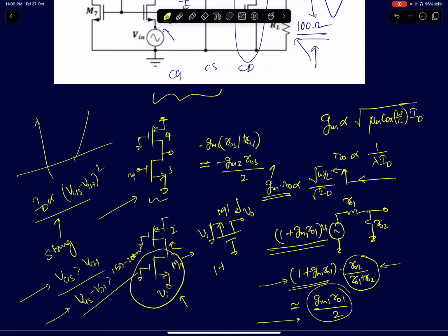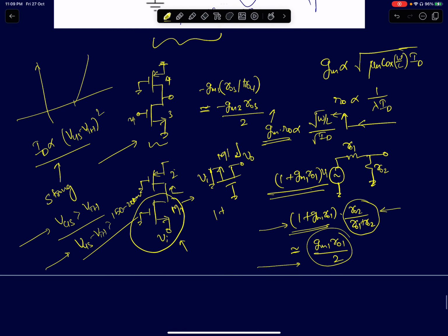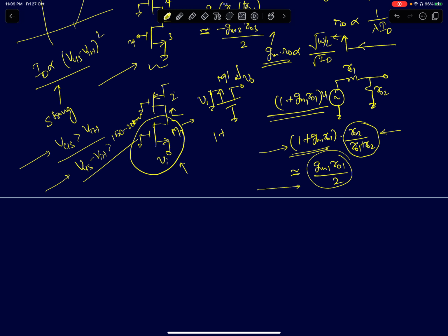But when you actually start designing circuits, you have to keep in mind that the actual MOS model is a lot more complicated than a square law device. You would have a dependence on different node voltages of the MOS device and more parameters than what we normally introduce. We just care about W by L ratios and oxide capacitance. It will have some additional parameters as well. So that makes the mathematical modeling complicated, so we have to rely on simulation software.